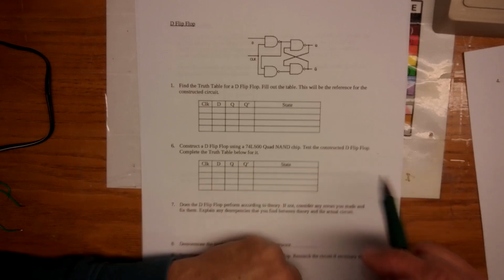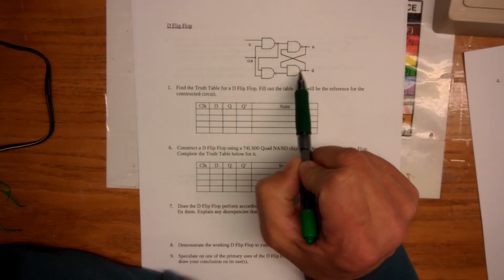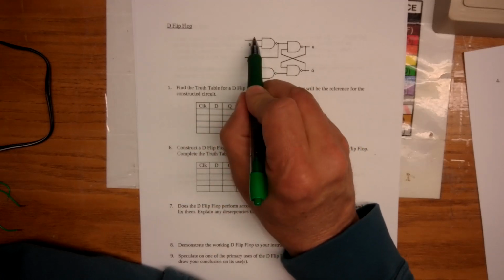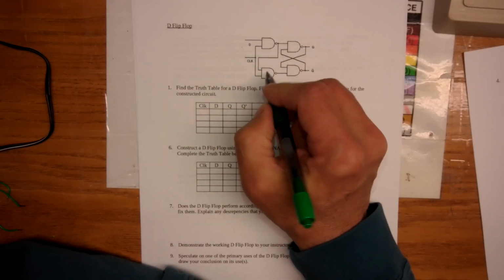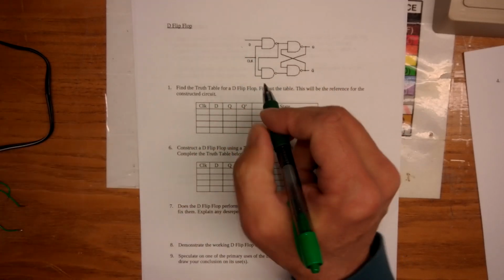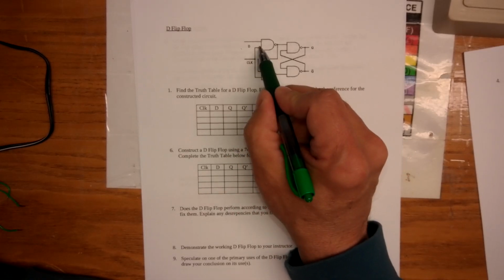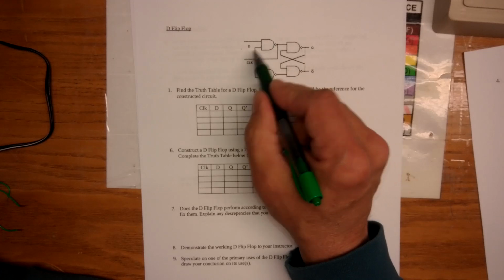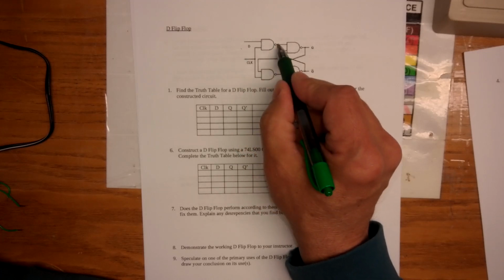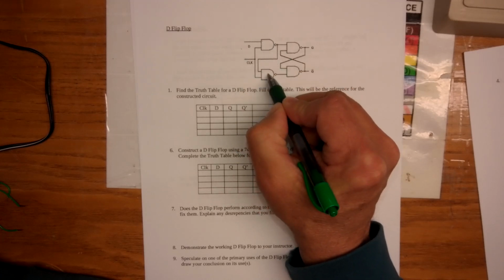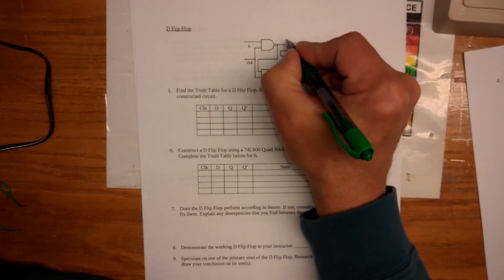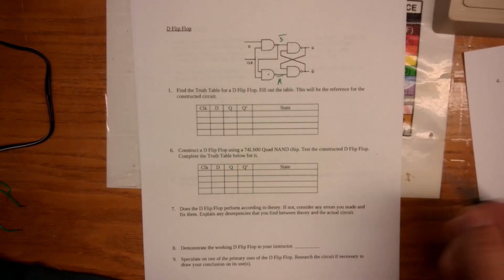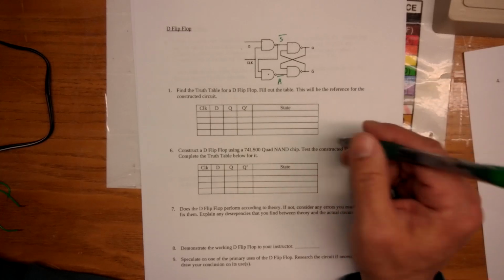The D flip-flop really just uses our 7400 NAND chip again. I have a single input, and the clock goes to both these NAND gates, and the output of this one goes to this input, as well as here's my basic SR flip-flop again. So I can just use my single 7400 chip, and I can go through and label it.